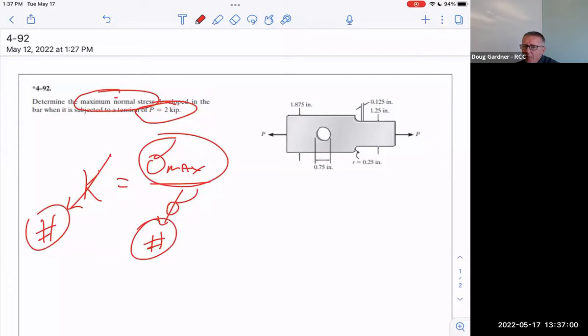Now, why would you do it that way? Well, this is probably a little more realistic because here's this weird part, and because you do all these calculations in the tractor that it's going to end up with 2,000 pounds of pull on it. You don't get to fix that, right? You're just stuck with that because of the motor. So then it's like, okay, well, how strong does that need to be? Should we use aluminum? Oh no, that'll snap off. Aluminum's PSI strength, remember, you can look that up in the back. The PSI capability of aluminum might not be good enough. And so we're going to need structural steel.